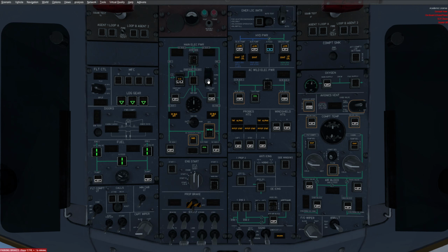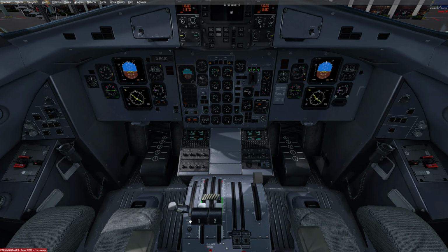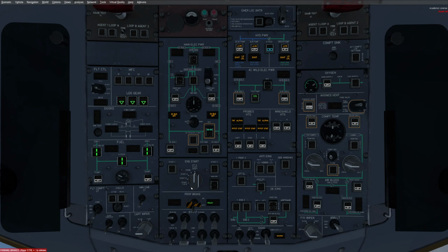We know what our fuel is. Our prop brake here is still off and guarded. Our gust lock we know is on. Our beacon we can turn on, tell people we're going to be firing stuff up. We're going to hit that little hydraulic button at the bottom of the parking brake right there. Then we're going to run back up and you'll see ready next to prop brake. That's important. So we'll open up our safeguard, we'll left click the prop brake to on.